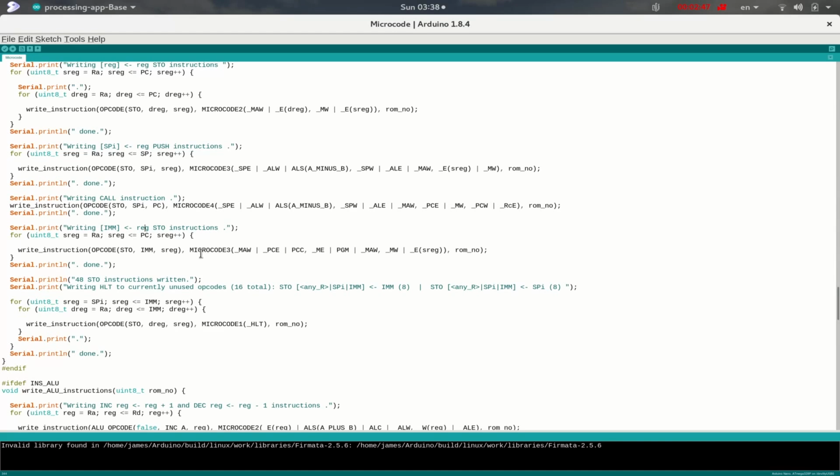And so we have here microcode, which consists of 3 instruction cycles. In the first one, we need to get the contents of the program counter, which are in fact already pointing at this immediate operand inside the program. We need to get that into the memory address register, and at the same time increase the program counter so that it now points beyond that immediate operand, and it's in fact pointing at the next instruction.